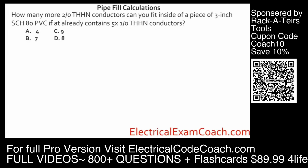The next 3 sample questions are going to go a lot faster. It's assuming that you've already learned how to use these tables. I'm not going to be showing them on the screen. How many more 2-aught THHN conductors can you fit inside of a piece of 3-inch Schedule 80 PVC if it already contains 5 1-aught THHN conductors?